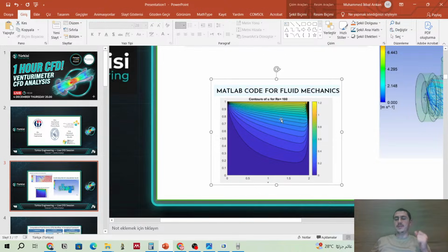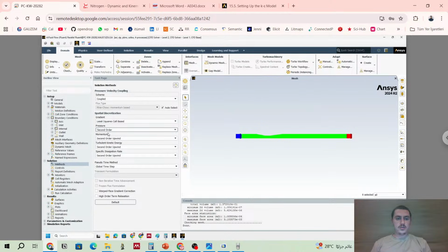You need to do something else. So what you do, you change the numerical algorithm. You switch it to something else, rather than second order upwind, something worse than this, so it will converge depending on the selection. So this also makes sense that you should have a good control of method algorithms.